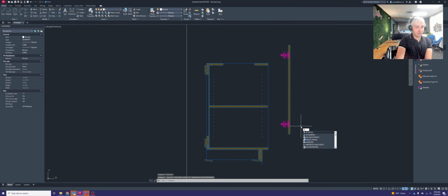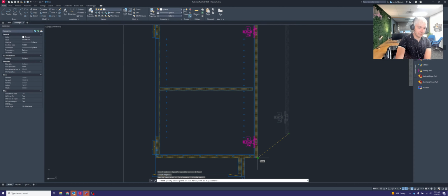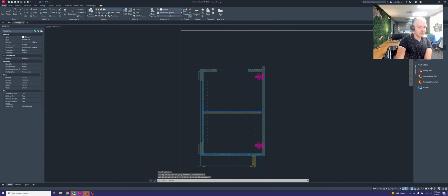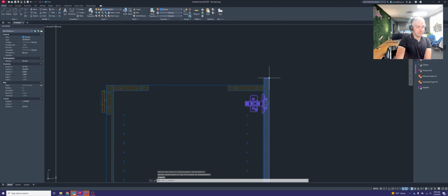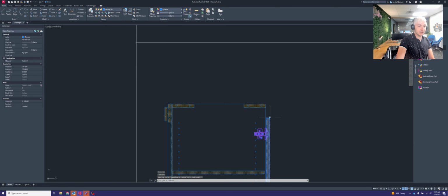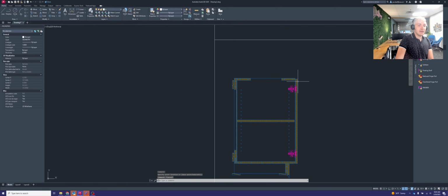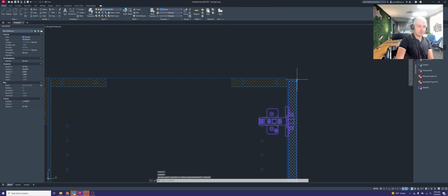We're going to use the move command once more. We're going to move this cabinet door, and this time we're going to use the front corner of the door, just like this, and snap it to this point right here. All right. Now, there is an invisible white dot there that does not print. It's there for you to be able to move that door up or down, or move it to where it needs to go. The door has a height adjustment too, which you just saw me move so that it snaps to that white dot.